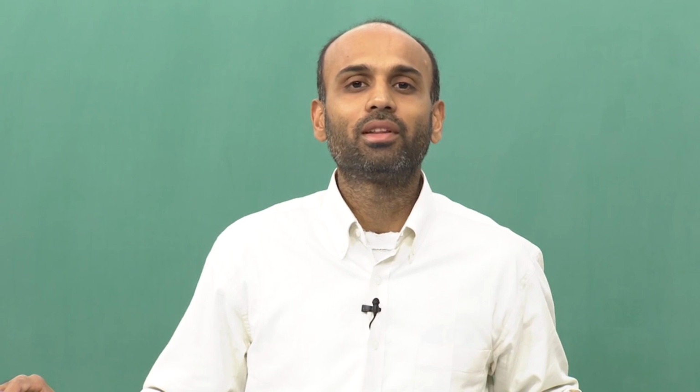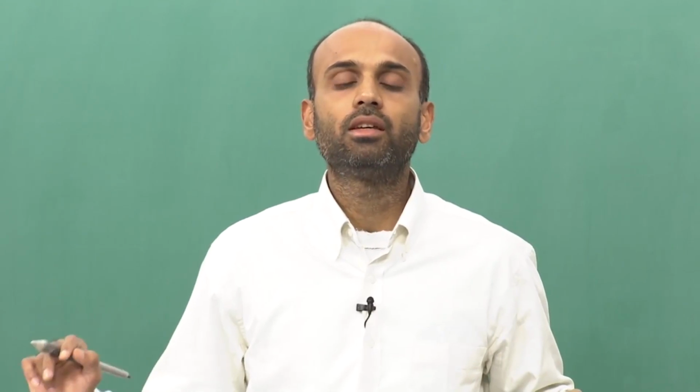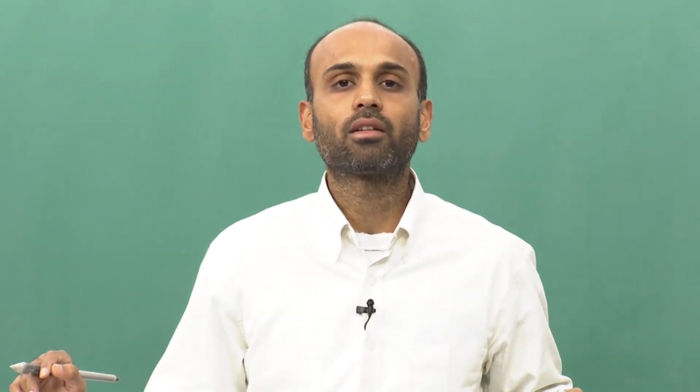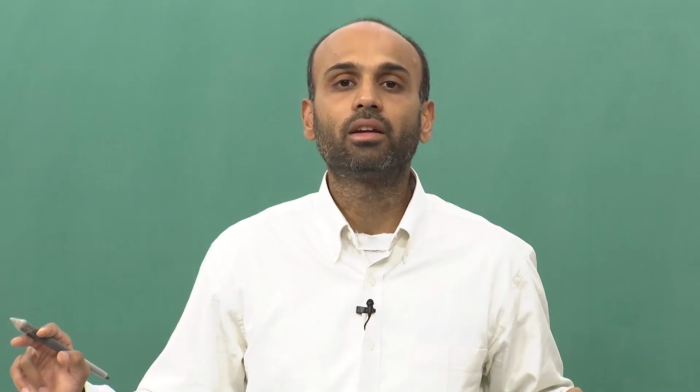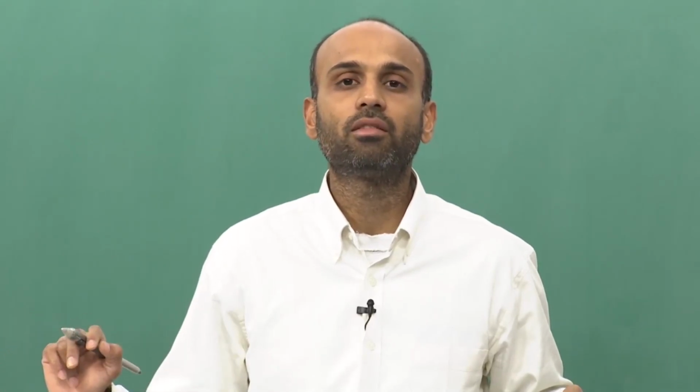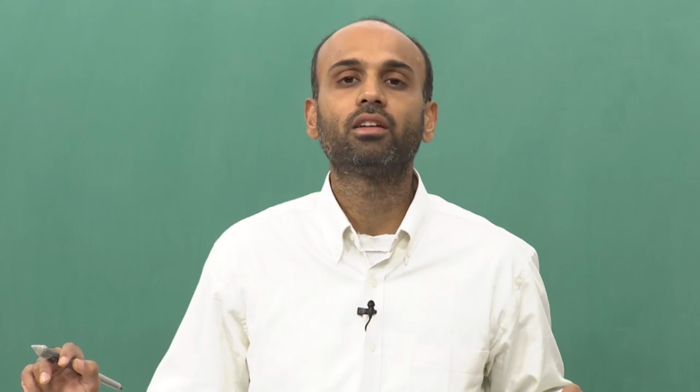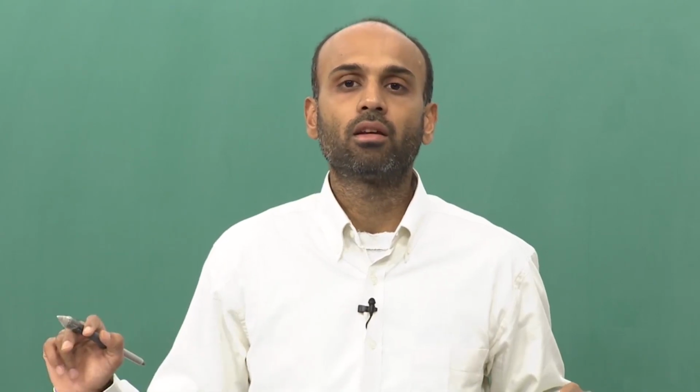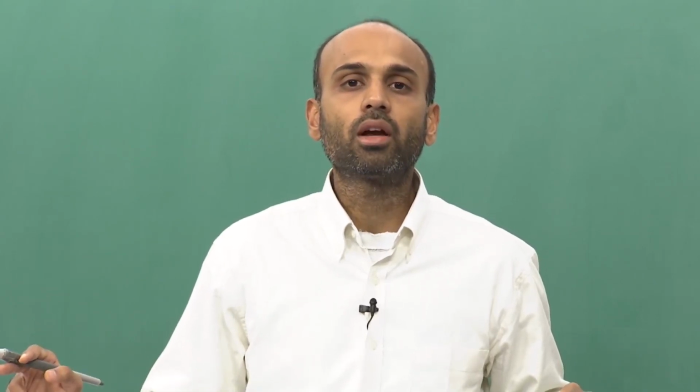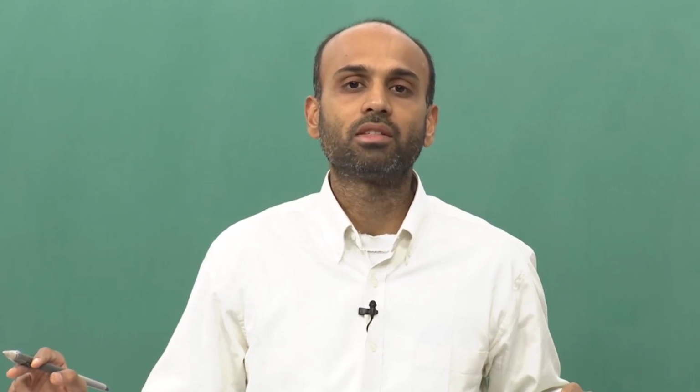Welcome to another module in this massive open online course on Bayesian MMSE estimation for wireless communications. So, we are looking at the LMMSE equalizer for a wireless communication system with inter-symbol interference. We have derived the LMMSE equalizer to remove the inter-symbol interference in a wireless channel. So, now let us look at the error for this MMSE equalizer.